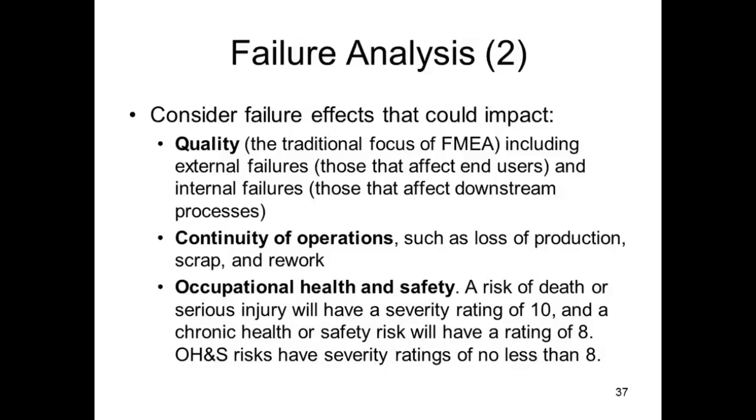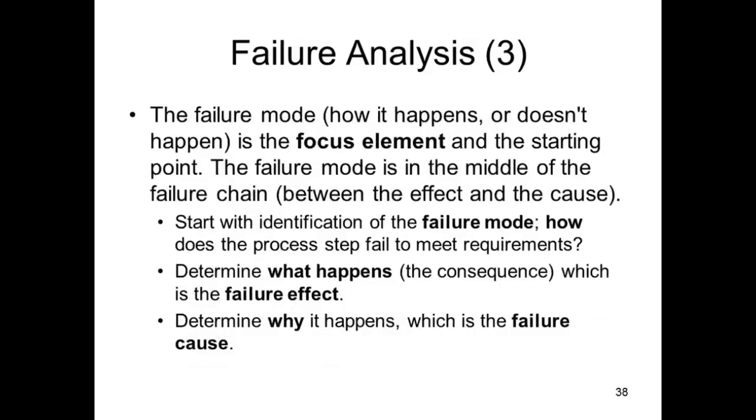If it can cause greater harm, my inclination, I'm not giving engineering advice here, but my inclination from a safety perspective is that if it's capable of causing greater harm, I would rate it no less than a 9. And an acute risk is defined as a 10. That's something that can cause immediate injury without any warning whatsoever. This is all given, though, in the AIAG VDA FMEA manual where they have severity ratings.